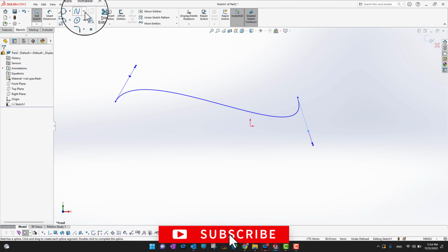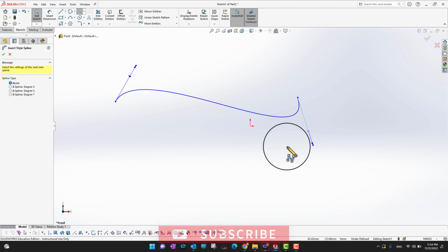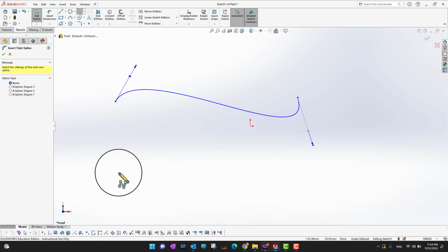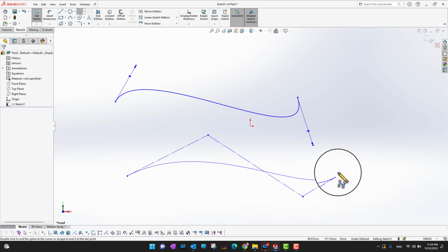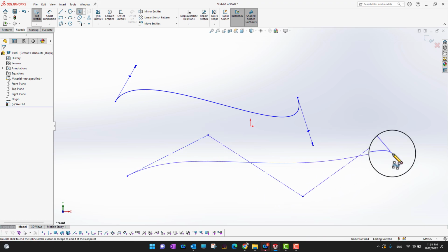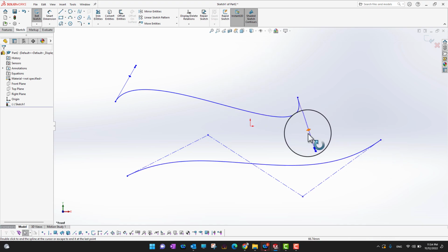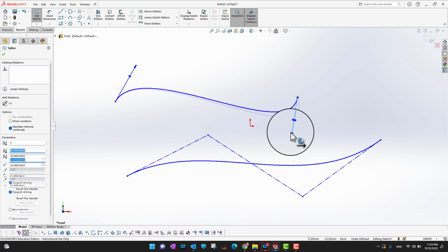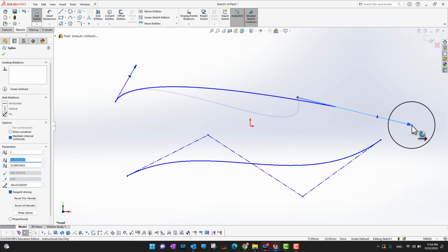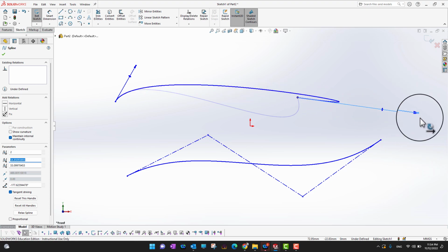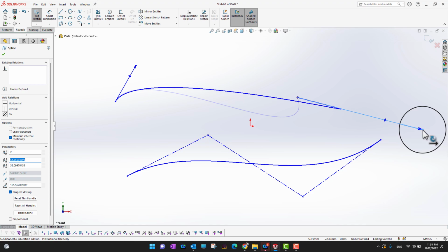Okay, I want to go back into the style spline. The style spline is a bit simpler and more advanced. You just need to draw the points: first point, second point, third point, and fourth point, and press the escape key. In the simple spline you can control the direction only by using these direction vectors. In this way, sometimes the shape can be weird or you don't have a lot of control.